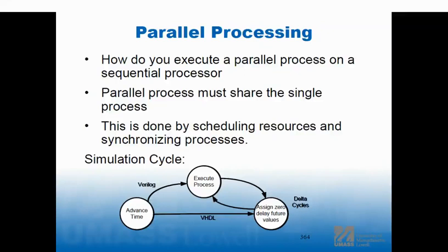So it uses delta cycles. A delta cycle says, I'm not done with the calculation, but I'm going to put that calculation at time delta 1. 1, 2, 3, 4. I'm still at 1100 nanoseconds or whatever the time in the simulator was, but I have to go a delta time and a delta time, right? To not advance it, but to keep adding to it. And then when all the delta times are depleted, I can advance potentially to the next clock cycle, the next period of the clock. And that's what delta time does.